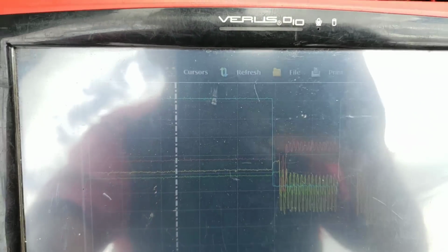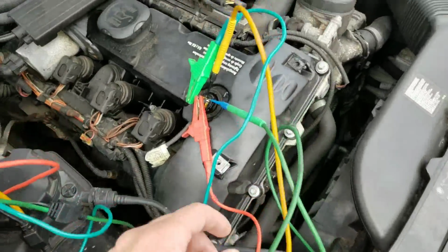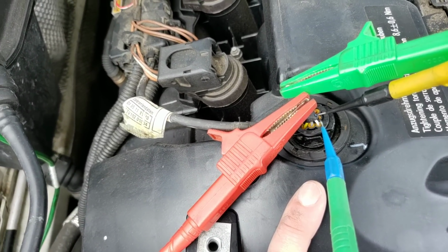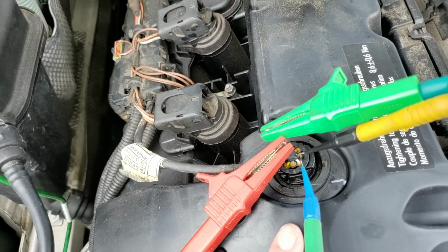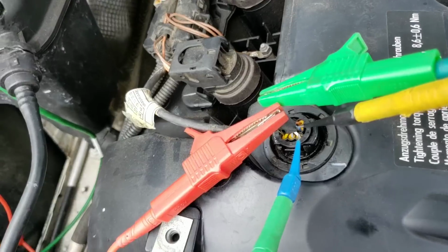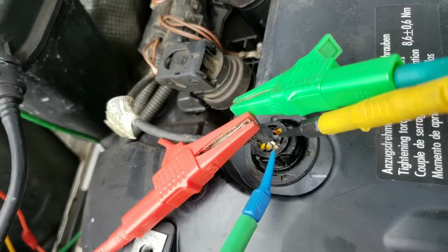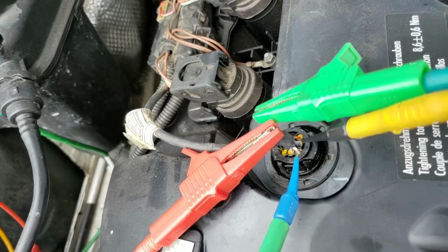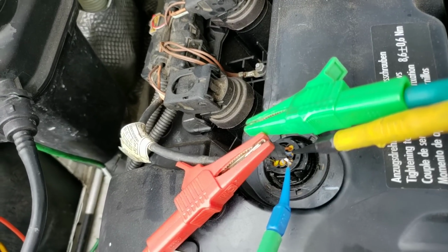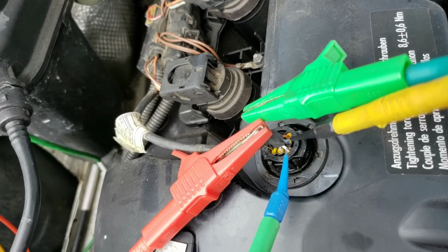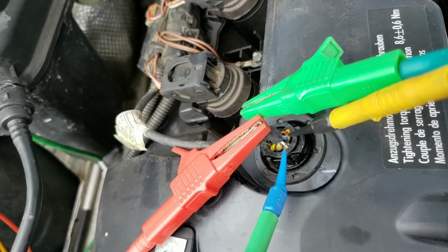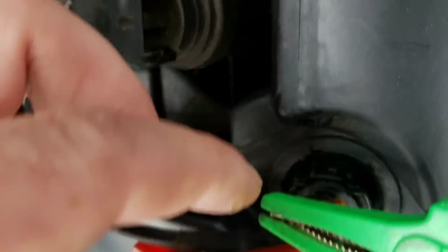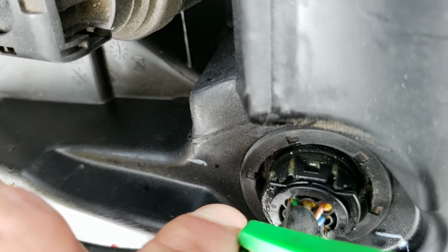What these sensors get is going to be one 5-volt reference, which on this one in particular is going to be on the gray line, and then your black line there is going to be your ground. We're tied into the other wires right now, which are going to be for the position sensing, and then we have a sensor ground and we have a static ground or a shielded ground also. So you'll have 2 grounds, one 5-volt reference. Your shielded ground, I believe, is going to be the brown on this side, right in the middle. Yes, it is.